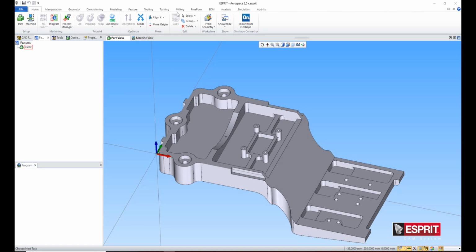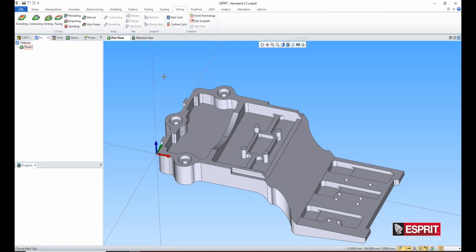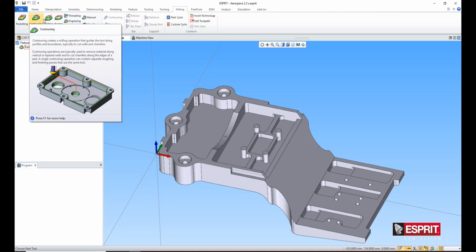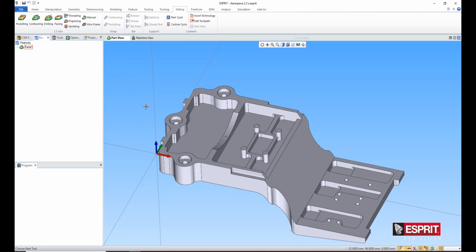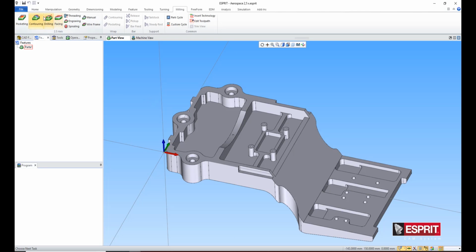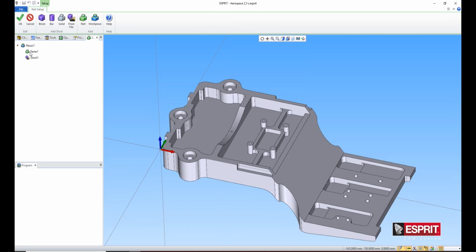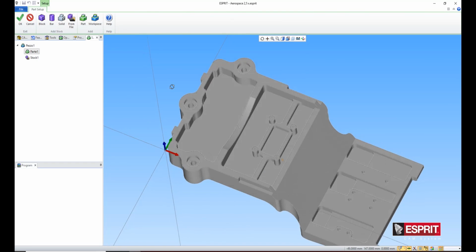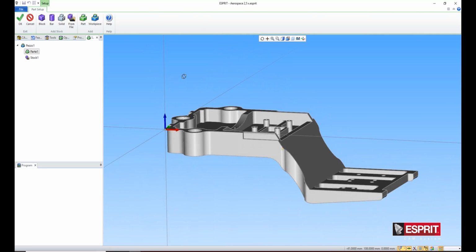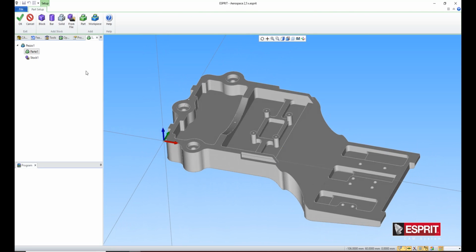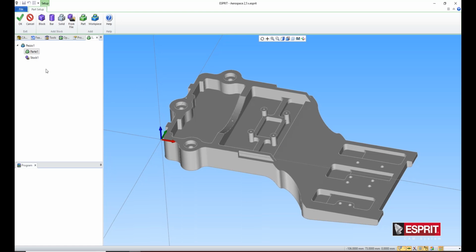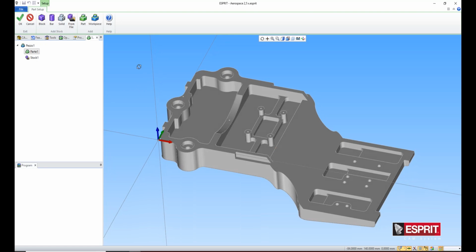We will now have an overview of the 2 and 5 axis milling cycles, such as pocketing, contouring, and drilling. Before starting, the user has to define the part to check any collision on, and the stock that can be a block, a bar, or you can import an external file. Once the part and the stock are defined, we can start with the milling operations.